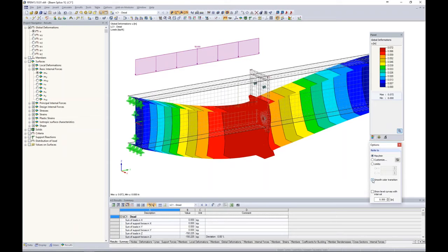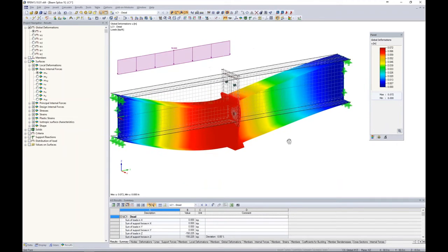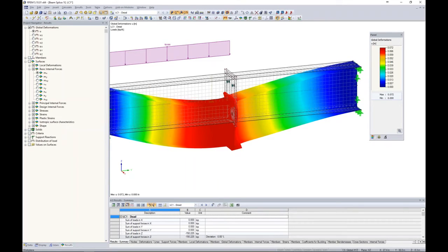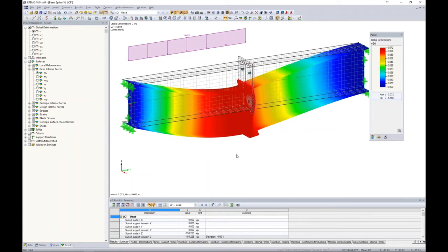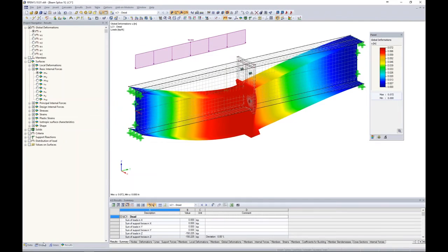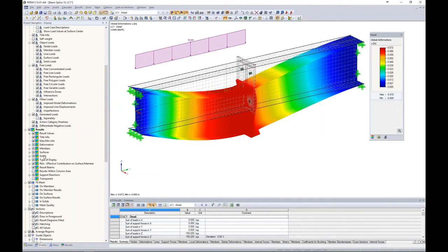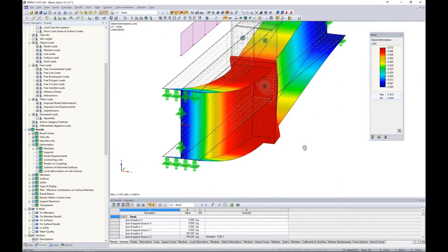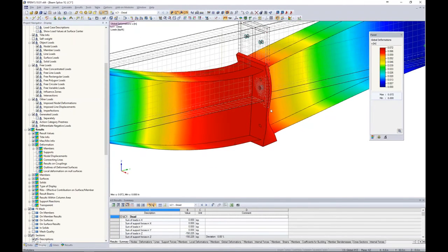So to me, I think the most important thing to automatically take a look at is deflections. Deflections are really going to show us if we've correctly defined our contact solids, maybe our FE mesh, and if it looks to about what we would approximate. So it's kind of a little bit difficult here to see our deformations and what's going on. So under our display tab, like I mentioned before, we have this whole results tree. And under deformation, I can actually choose this option to outline my deformed surfaces.